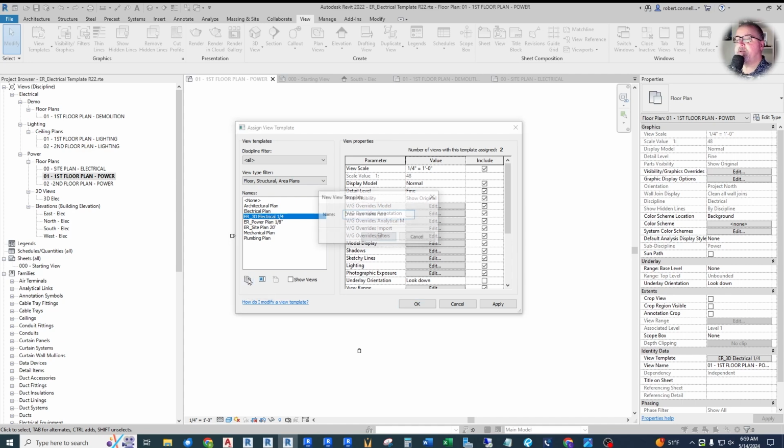So we will duplicate this, and let's get the ER section electrical. And let's go ahead and do this one at 1/8 inch. Again, you may want to set up a couple. Depends on, again, how you use these in your designs. Detail fine. I like fine on a section as well. And then we go into model display.